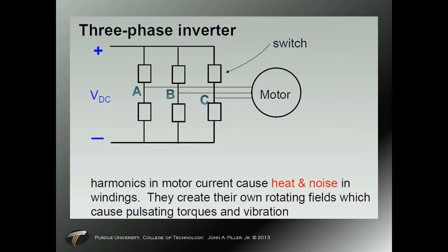And just as the diodes of the three-phase bridge circuit are forward biased in order to allow the waveform to create the correct voltage potentials of VAB, VBC, VCA, and VAC, the switches will be controlled via a microcontroller to activate in the proper order and create a step waveform that simulates a sine wave output. The next slide has that waveform.